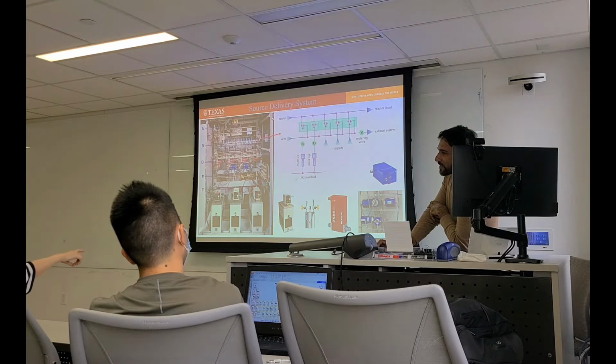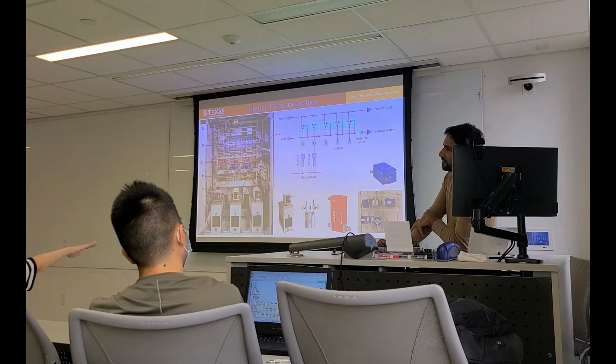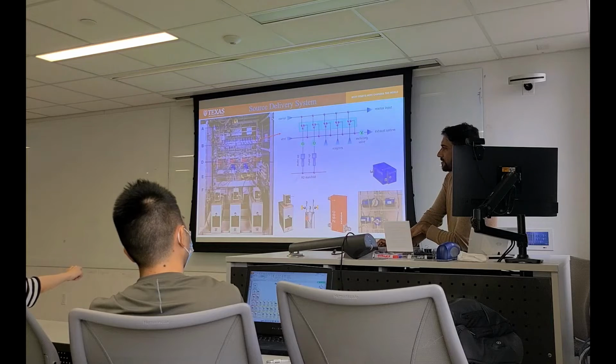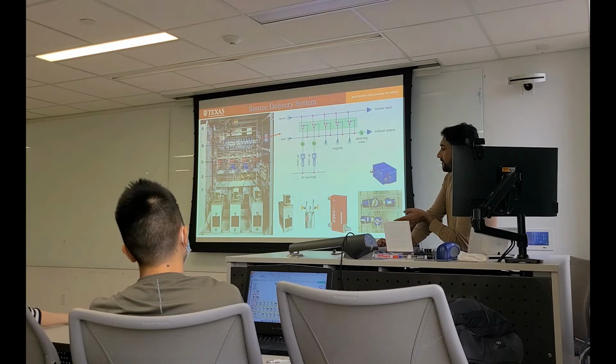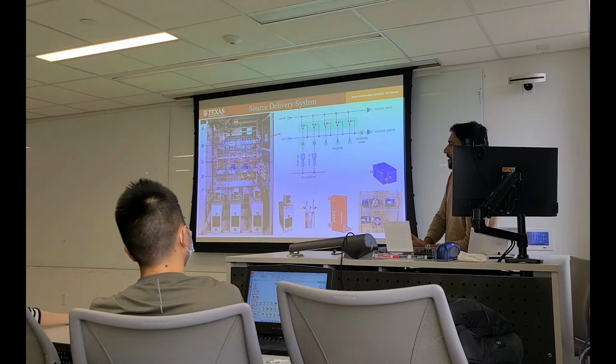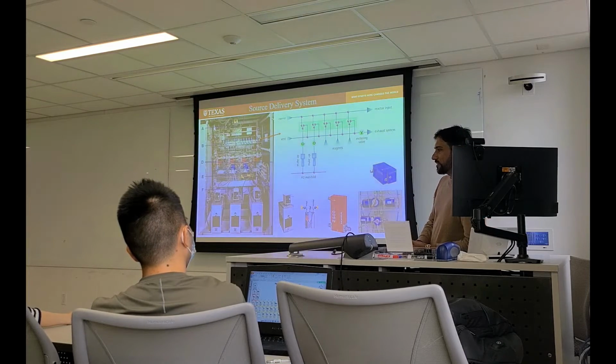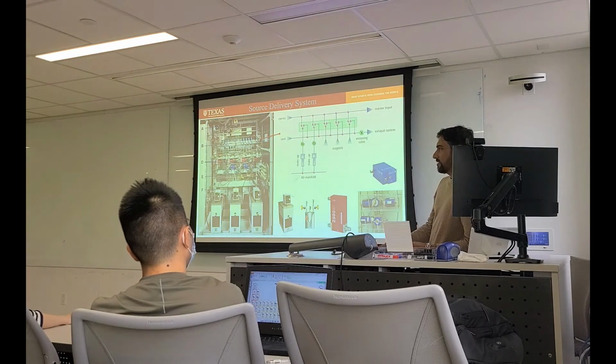I have a question. You said the gas flows in. Only the carrier gas? The carrier gas can be argon, nitrogen, or hydrogen, so it depends. For trimethyl indium we cannot use hydrogen because hydrogen etches the indium, so we use nitrogen. Depending on the metal organic source, we need to decide what kind of carrier gas to use. Mostly hydrogen, nitrogen, and argon are used.